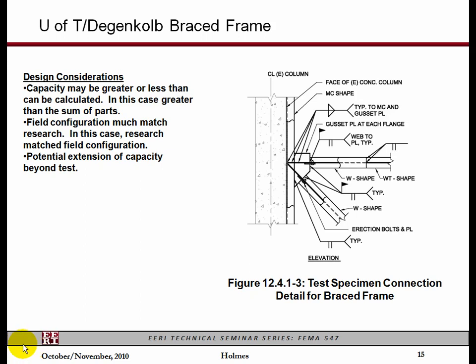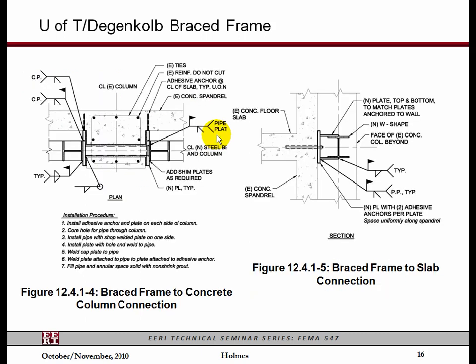that problem. Now, the interesting thing is when you come up with systems like putting a steel brace frame inside concrete, it's very hard to calculate what the resulting stiffness and strength is. In this particular case, it was very interesting because the sum of the parts was greater than you would ever calculate. So the capacity of this combined system was greater by test than you could possibly calculate. So it turned out to be a very good, test-efficient system that was developed.